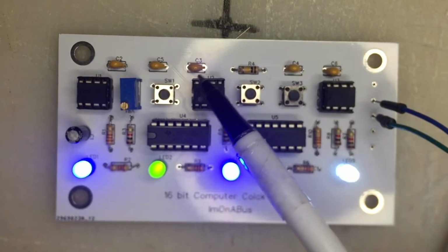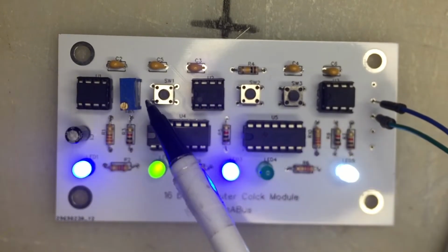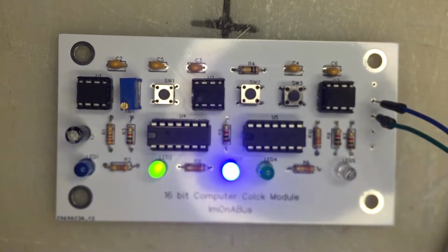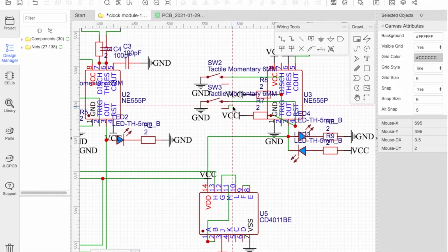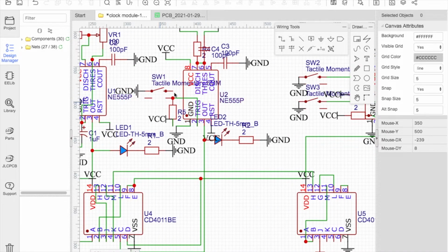And so you might have noticed that the two circuits with buttons hooked up to them aren't working. This is because in the PCB design I switched the buttons around. Right now they're not the way they should be. So the 555 timer should be hooked up to this pin of the button instead of this pin, and same goes for this button. So instead of only being connected to ground when I pushed the button, it was always connected to ground, so only one was ever going to be set. Same with this. This was always connected to ground, so the LED was always on, because as far as the 555 timer was concerned, I was always pushing the button.